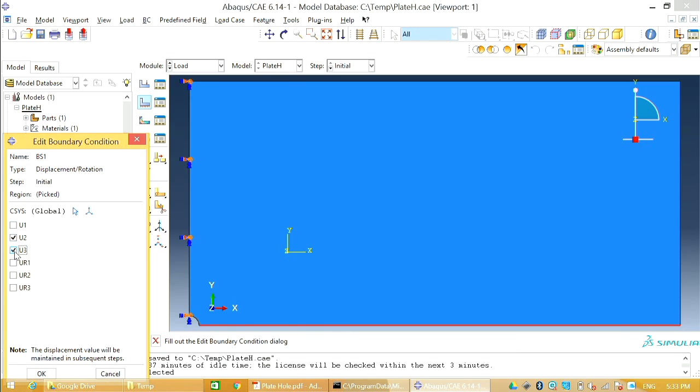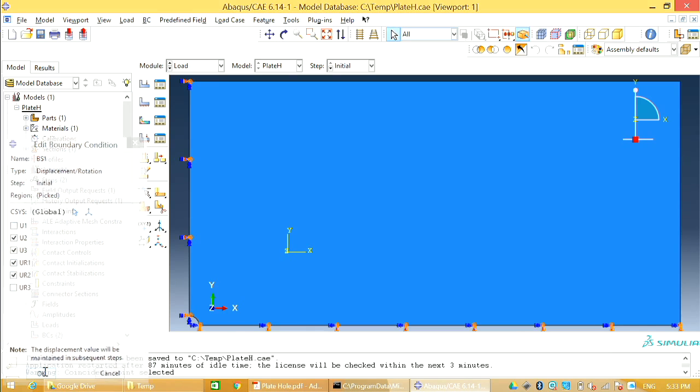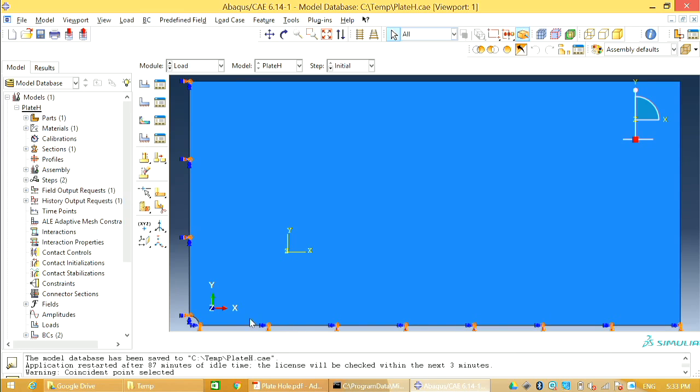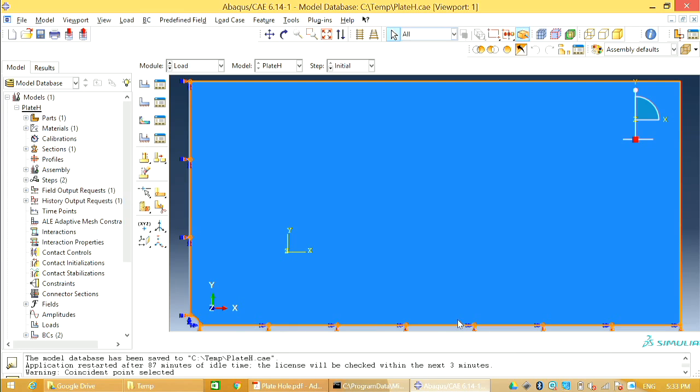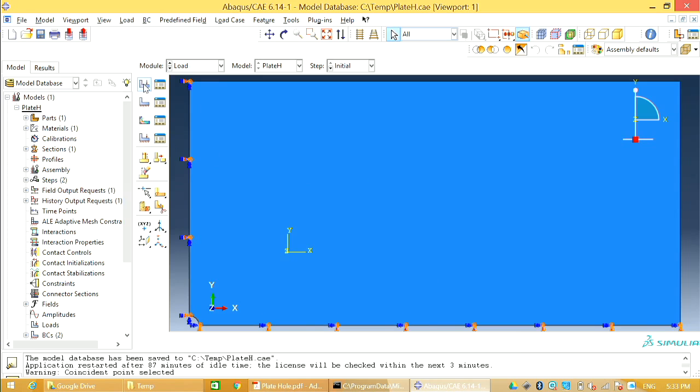By doing this, we are replicating or applying the symmetry of the problem, okay? Basically, just as an example, this line cannot penetrate the quarter of the plate that is below, right? This is basically what we're doing, making physical sense of this. So what is left is just to apply the load.